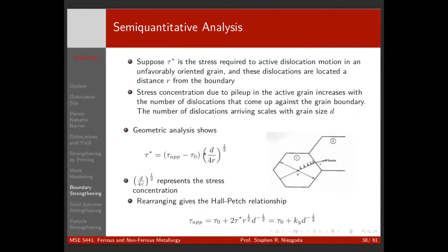Remember, we said that a high-angle grain boundary can be imagined as a very complicated array of dislocations. For low-angle grain boundaries, we had these nice array structures. But as the character of the grain boundary got more complex, we didn't have a nice simple grain boundary model for it anymore. But anyway, as you can imagine, it's quite difficult to get a dislocation through a grain boundary.